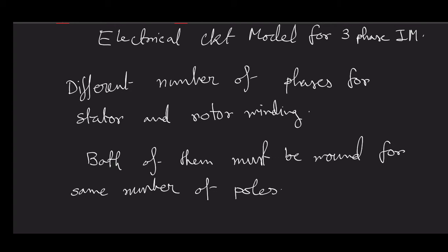For any balanced system, like we did for the three-phase synchronous machine, we go for a balanced analysis. But if the rotor and stator are not of equal phases, how can we go for a balanced per phase analysis? The matter of concern here is getting a per phase circuit.